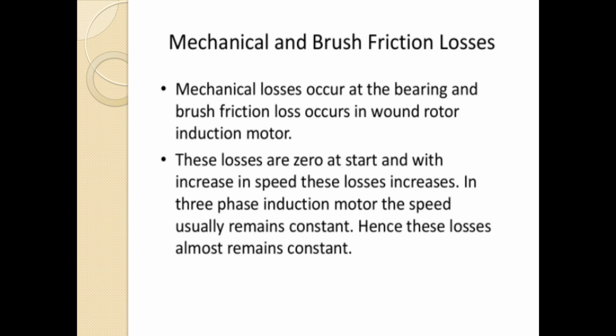And another one is mechanical losses. The mechanical losses consist of frictional losses and windage losses. In an induction motor the speed drop is very small, so the mechanical losses are part of the constant losses. Constant losses are equal to iron losses plus mechanical losses.